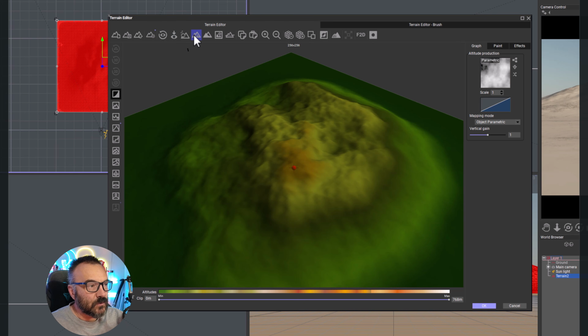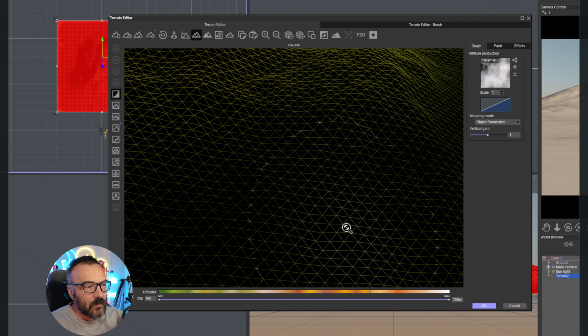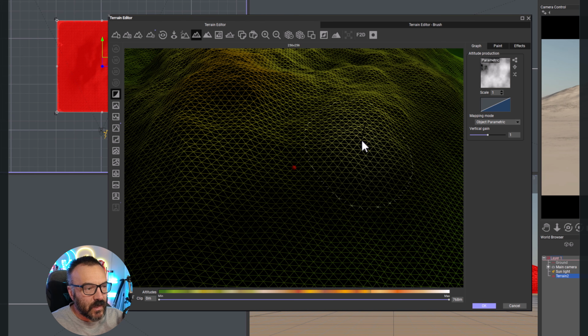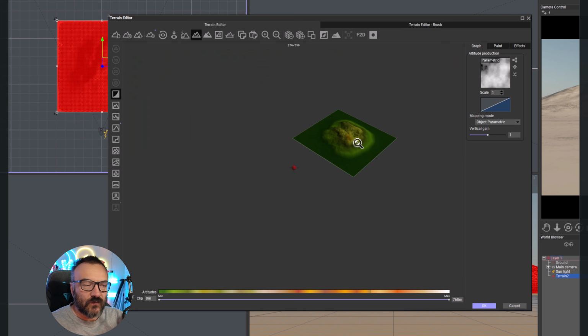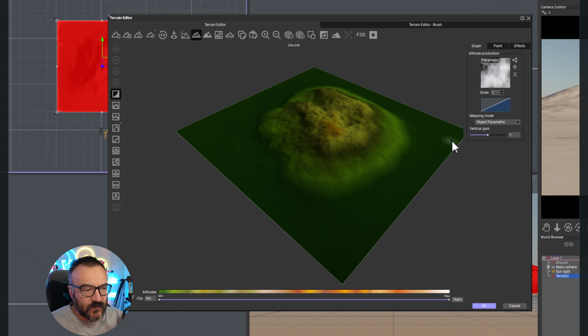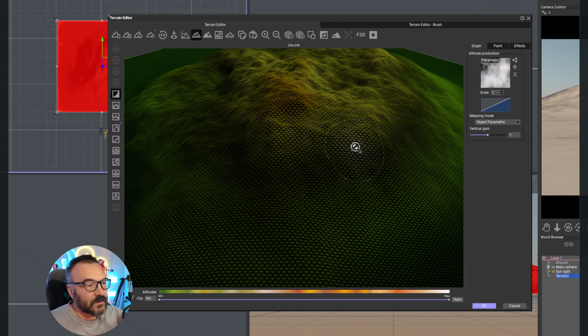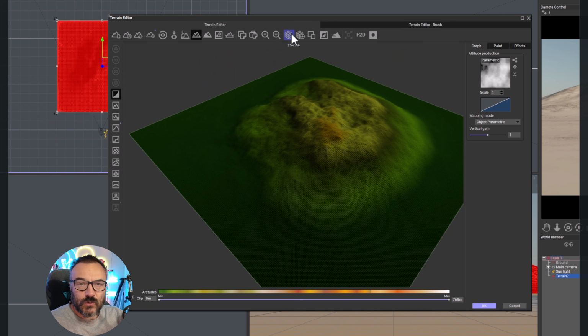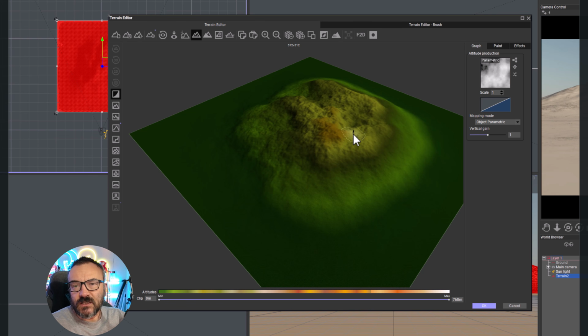To preview this, we can click on our preview mesh, and you can see right here we have it. See these points which connect all of these triangles? Each point represents the mesh, 256 by 256. So it means we have 256 points of the mesh in X and Y. We can increase the resolution by doubling, and it will increase details. That detail will not necessarily work on a fractal, it will just work as a preview for the fractal, but generally you can increase it.